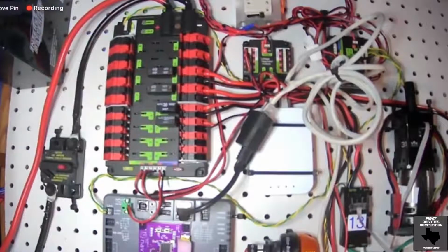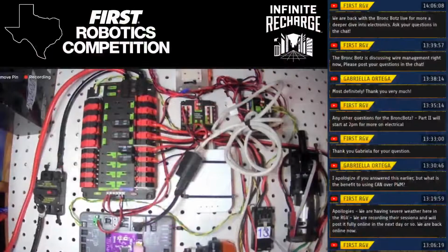You can determine which type of breaker to use based on how much load you're expecting on your motor, which is something we'll talk about how to calculate later. But it's incredibly important. For example, you do not want to hook your drivetrain up to a 30 amp breaker. It wants to be 40. But also, you probably don't want to hook your intake up to a 40 amp breaker because that's a waste of power. Again, amps are determined by the motor because the motor is the resistor.